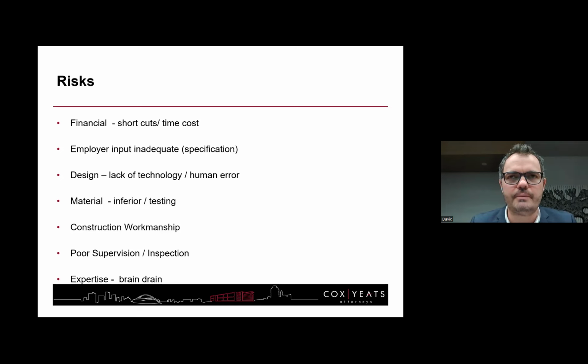In terms of the Engineering Professions Act and the regulations attendant to it, it clearly distinguishes between supervision and inspection. Supervision is your resident engineer that sits on site and actually watches what happens and inspects what happens closely. Inspection is completely different. That is where your design engineer pops onto site once every 2 or 3 weeks, walks around, looks at things generally, speaks to the contractor generally, and relies on the contractor to feed back information.